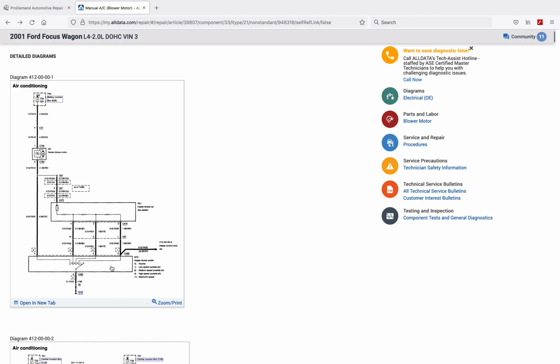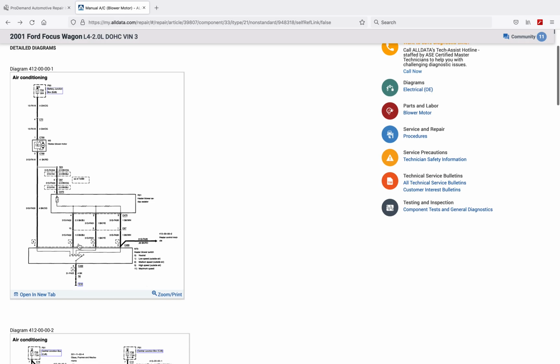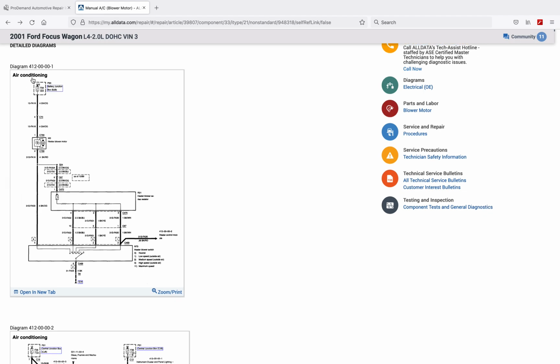We'll go to position 2 here, which says medium speed on the vehicle. I connect this to position 2. Now when I go to position 2, 1 was here, 2 is here. I'm going to go from power supply to the blower motor. From the blower motor, I'm going to go through 1 resistor after the blower motor and a second resistor for medium low speed. When I come out of pin 2, basically you can see I've cut one of the loads out in the series circuit given the layout of the diagram. As a result, my total resistance in the circuit goes down, and we can infer with basic mathematical reasoning that amperage goes up, fan speed is going to climb.